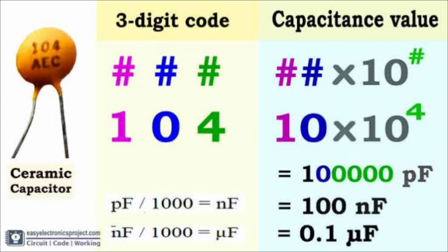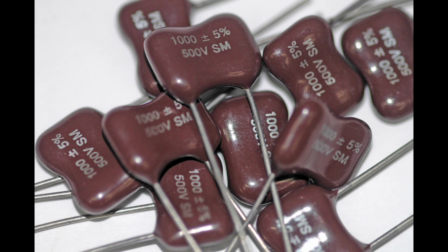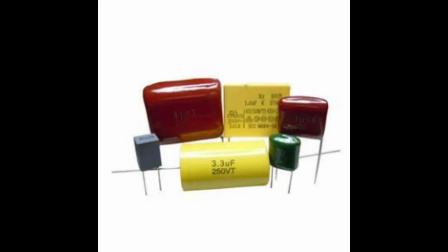Mica capacitors use mica as a dielectric material. They are very stable and have low losses. They can operate on a heavy voltage rating from 100 volt to 10 kilovolt with a capacitance ranging from 47 picofarad to 3000 picofarad. Due to their high voltage and power handling capabilities, they are used in RF broadcast transmitters, amplifiers, high voltage inverters, and resonance circuits. Film capacitors.